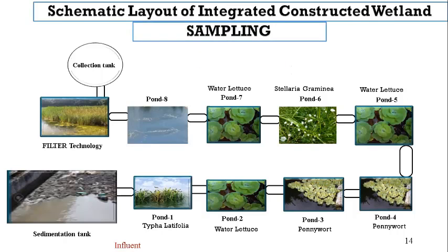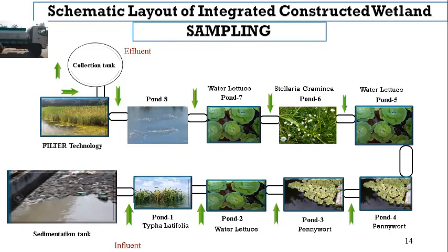The layout of the wetland system leads towards the sedimentation tank, then to a constructed wetland comprising 8 compartments where wastewater quality is improved by remediation. The quality of effluent from the constructed wetland is further improved by filtration, irrigating, and cropping for land treatment and effluent reuse.